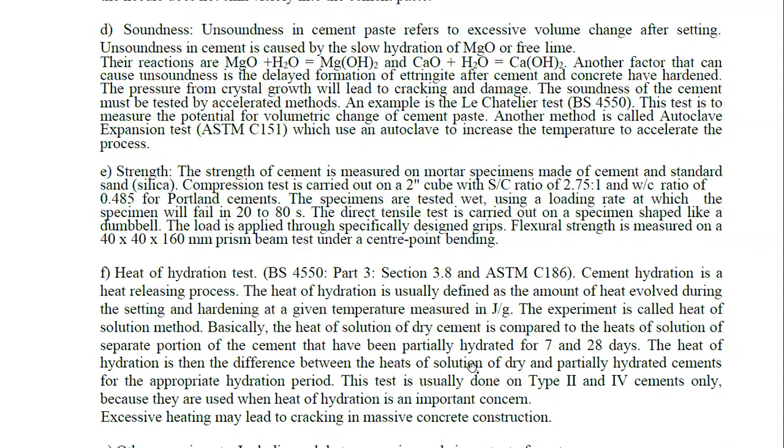So basically heat of hydration जो होगा ड्राई सीमेंट का, कंपेयर करेंगे आप 7 और 28 डेज के पार्शियली हाइड्रेटेड सीमेंट से. Heat of hydration is the difference between the heats of solution of dry and partially hydrated cement for the appropriate hydration period. This test is usually done on type 2 and type 4 cement only because they are used when the heat of hydration is an important concern. Type 2 और type 4 cement में heat of hydration test basically किया जाता है just because they are used when heat of hydration is an important concern.